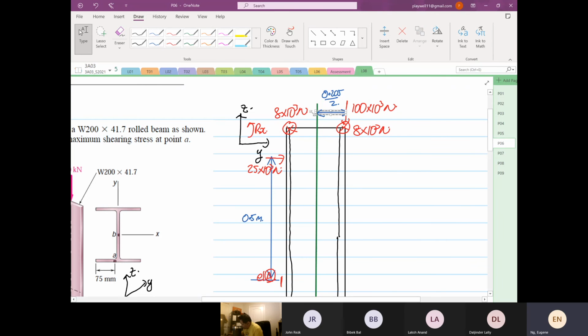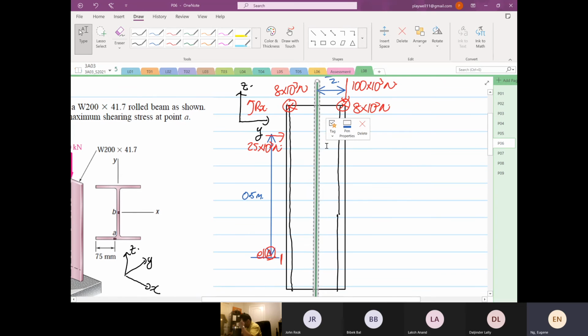Okay, I've been teaching this for quite a while now. I'm not saying that you guys, but I don't want you all to make the same mistake. It's a very common mistake. A lot of students will say, "Oh, Eugene, if that's the case, this is the perpendicular distance." No, it intersects the what? The neutral axis. Whereas the 25, the perpendicular distance did not intersect the neutral axis. That's why you use towards the element.